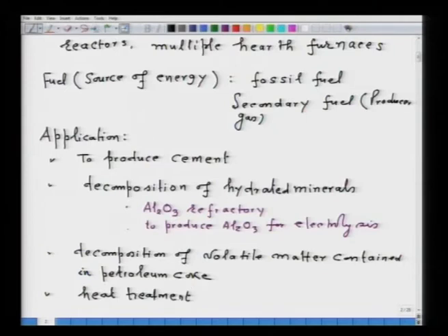However, in a strict sense you do not call it calcination, but since you are applying the heat below the melting point of the material, well, you may class it as a calcination, as a heat treatment, and you may not class it, that does not matter, but all that you require is a solid state transformation from room temperature to another temperature. And so, these are the certain applications of calcination.